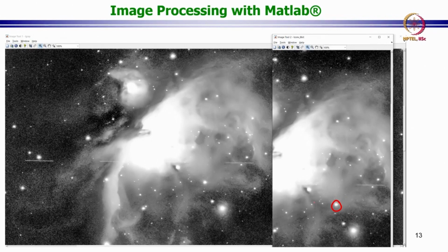Now this mean filter can also blur very sharp images. So sometimes it may be desirable, sometimes it may not be desirable. So whether this kind of convolution is even desirable or not is something you have to determine on a case to case basis. Here my use of the mean filter is essentially leading to a little bit of smoothing of the two images, whereas in other cases where there might be very sharp images, it might also lead to blurring. Okay.